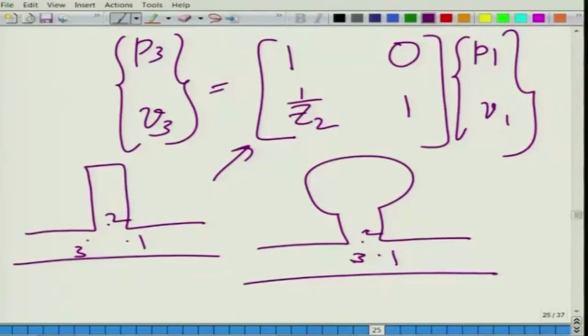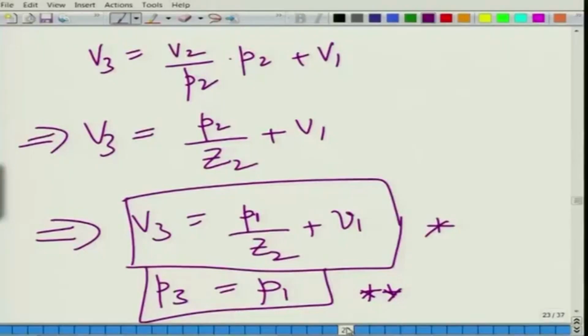Then we introduced things like state variables, and we had an electro-acoustic representation of an acoustic system. And then we got acquainted with a term called transfer matrix, also used in electrical circuits. There is yet another form of matrix representation used very popularly in electrical circuits, and to a lesser extent in acoustics, but nevertheless important, and that is your impedance matrix. Since we are discussing that, let me just introduce that part to you.